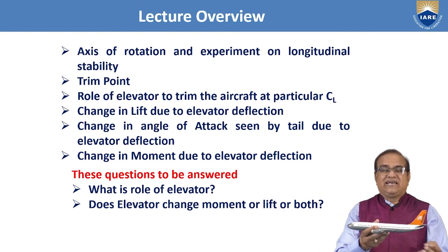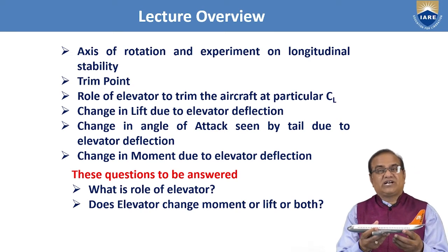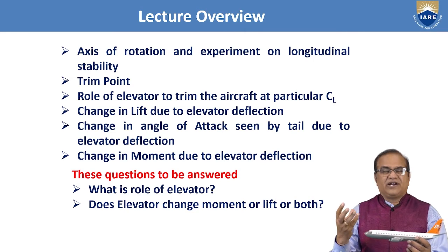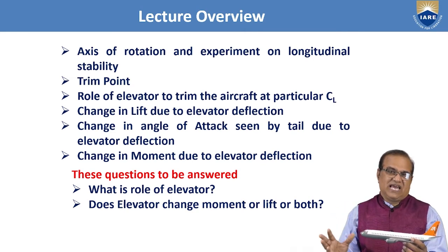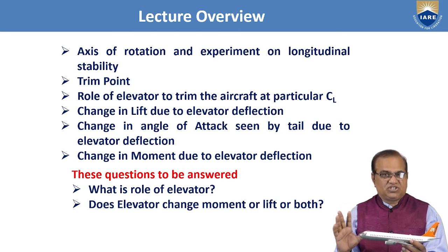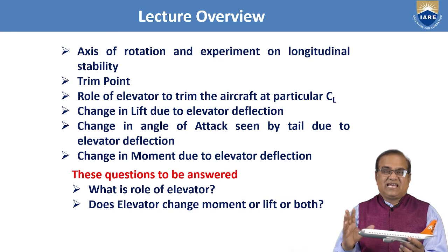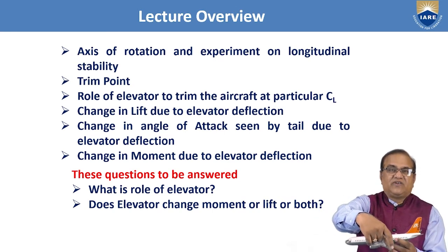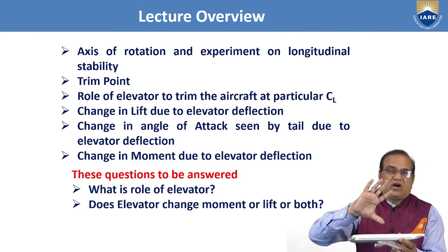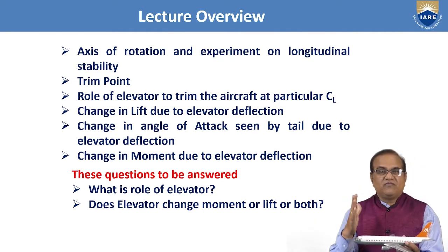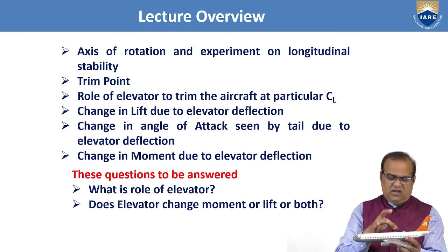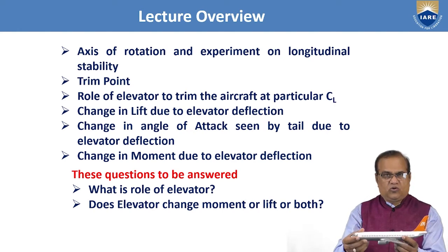Also, once I talk about the control, we have the 3 typical controls of the aircraft. One is the elevator, which makes pitch up or pitch down. Another is the aileron. Ailerons are fitted at the wing tip, on both sides, and they are operated in differential form. If one goes up, the other goes down. In this way, the work of the aileron is to give the roll.